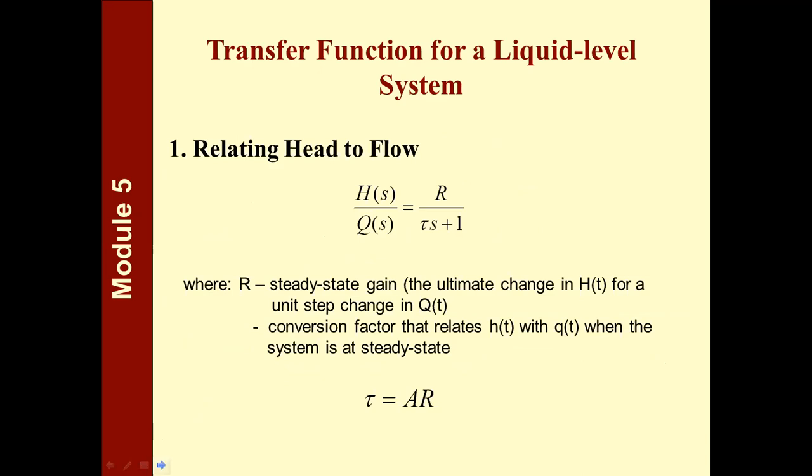Now we go to the transfer function of the liquid level system. If you notice in this slide, you don't see any derivation anymore of the process by which we can get this particular transfer function of the liquid level system. This is the transfer function of a liquid level system that relates the head, or the level of the liquid inside the tank, to changes in the volumetric flow into the tank.